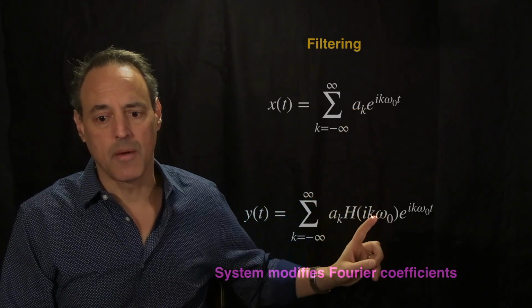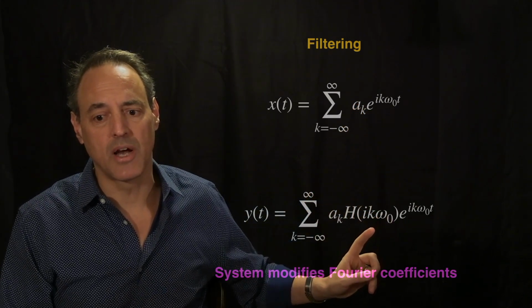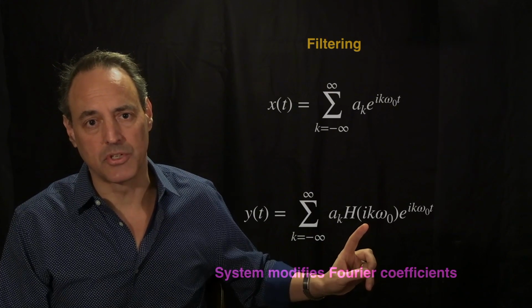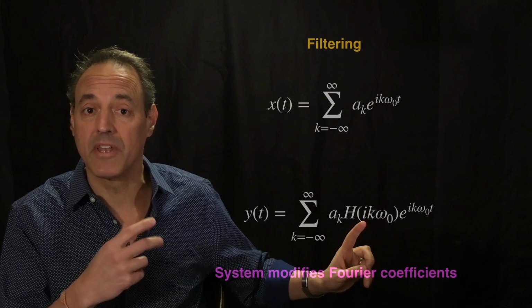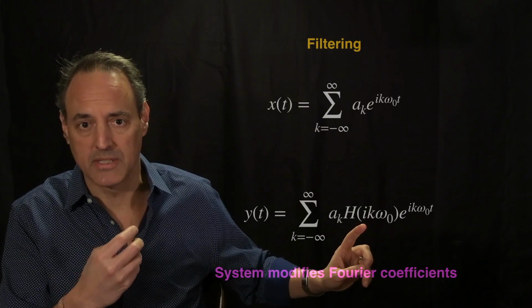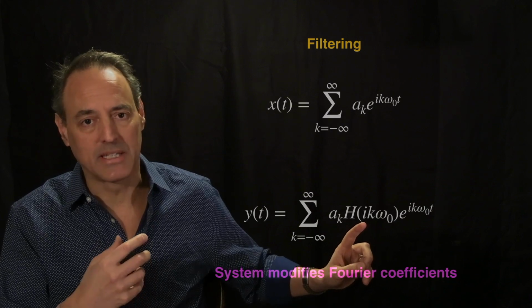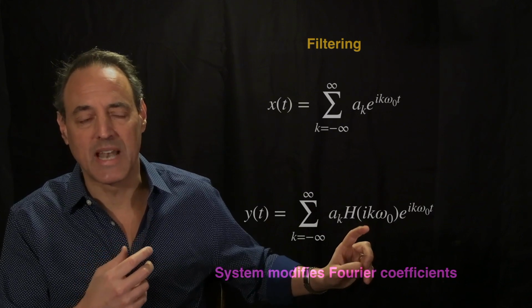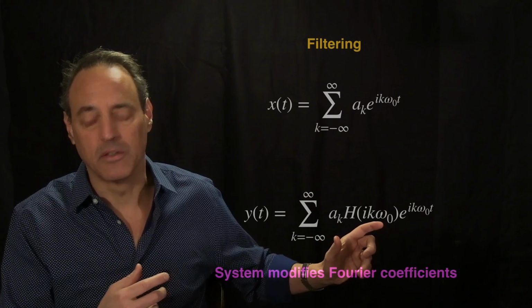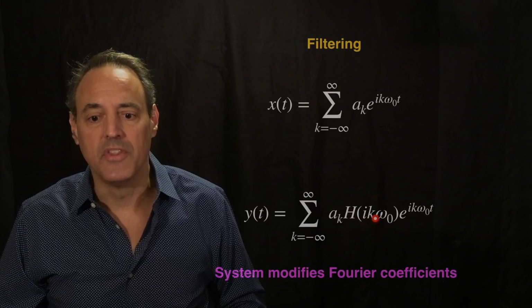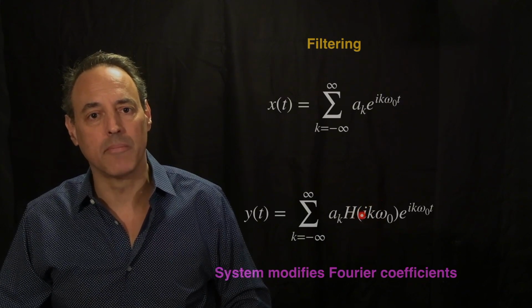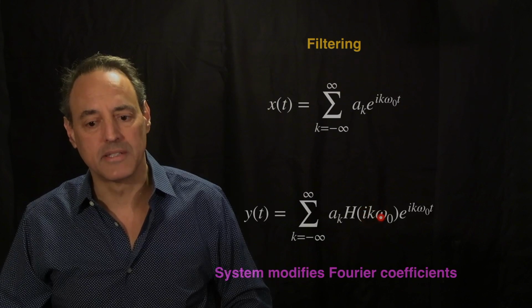Now, when you pass through an LTI system, these exponentials that we have here are actually eigenfunctions of the system, and upon passing through, they produce some kind of product here, which is some h, which is determined by the fundamental response, the little h. So once you give it an impulse response, that's the little h. That response produces an output of how this signal is going to look back in the time domain. So here, this h gives us essentially what happens to every single Fourier component going through our LTI system.